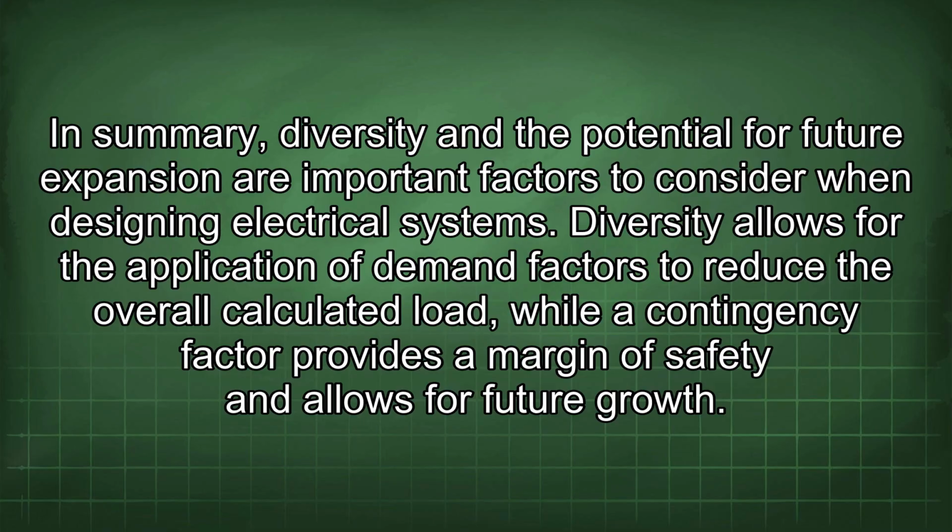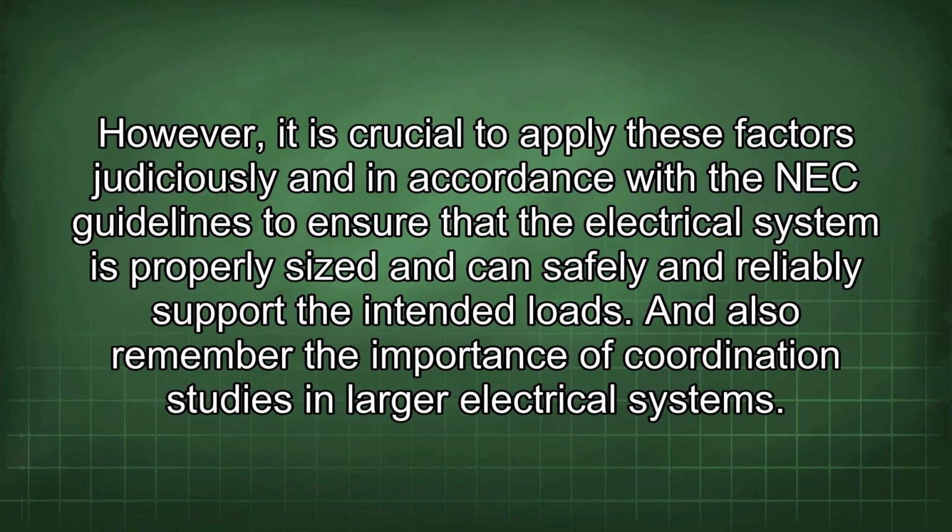Diversity allows for the application of demand factors to reduce the overall calculated load, while a contingency factor provides a margin of safety and allows for future growth. However, it is crucial to apply these factors judiciously and in accordance with the NEC guidelines to ensure that the electrical system is properly sized and can safely and reliably support the intended loads.